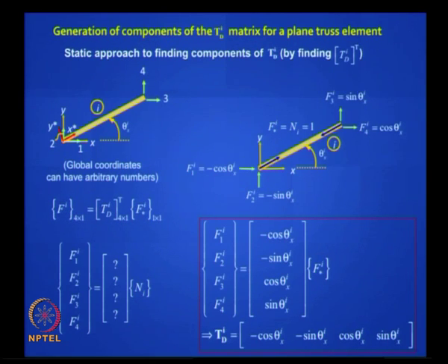You remember this. In this procedure what we say is, if you have a unit force in the element, say unit tension here, then necessarily at the two ends you need external forces to satisfy equilibrium, and the relationship between the element level force and the end joint level forces is given by this matrix, which is TD transpose. But you really do not need this, since you know that it is minus cos theta, minus sin theta, plus cos theta, plus sin theta, okay.